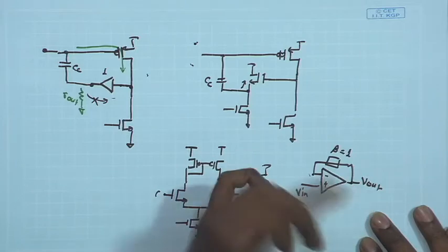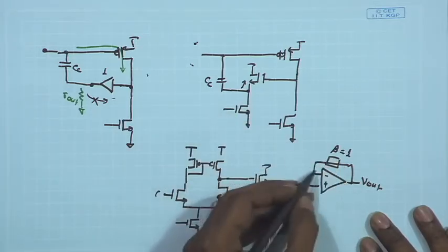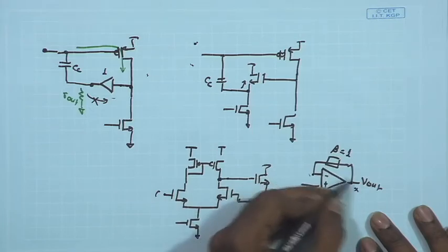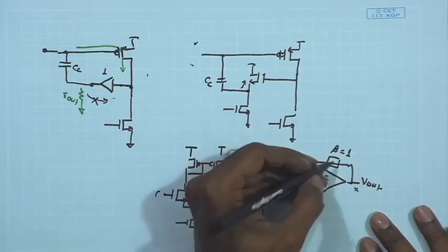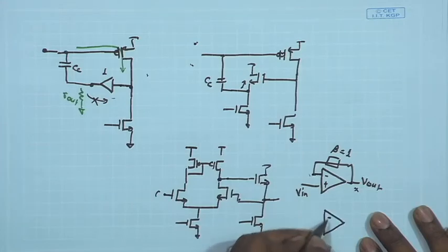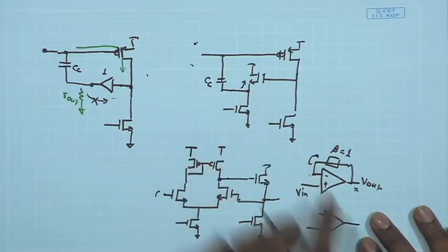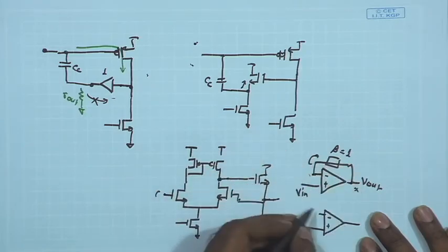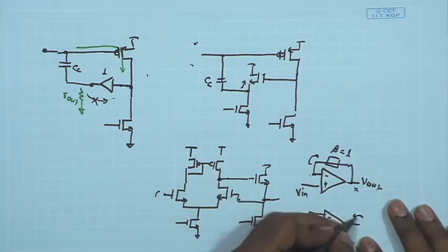And in order to find out the open loop impedance and hence the closed loop impedance, we know that we can just put an open circuit over here, because looking from the input port of the feedback network, I have a series connection at the output point. So, I can open circuit it, and looking at the output port of the feedback network, the other terminal is a shunt connection. So, I can just short circuit it or put in an AC ground. This is the equivalent open loop circuit corresponding to the voltage follower, and now I know the output impedance for this particular stage.